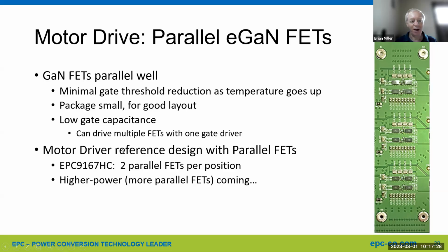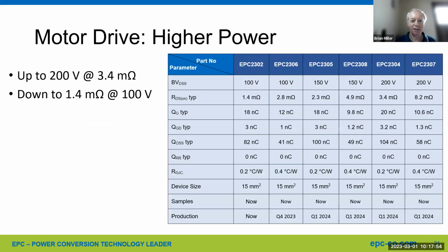So we do have one motor drive reference design that has parallel FETs, and that's the part number right here, 9167HC for high current. And that's the board over here showing 2. And we do have reference designs with even more parallel FETs coming. I think the next one might be 4 parallel FETs per position to get even higher currents. Okay, so that covers current.